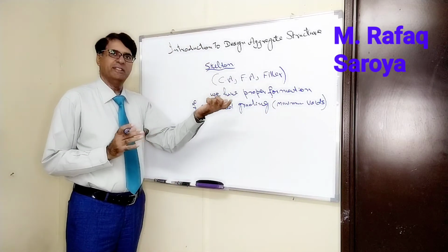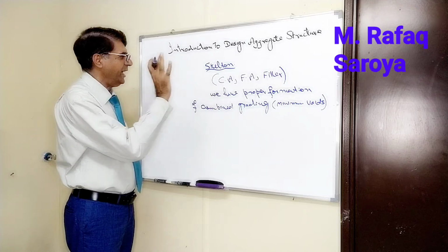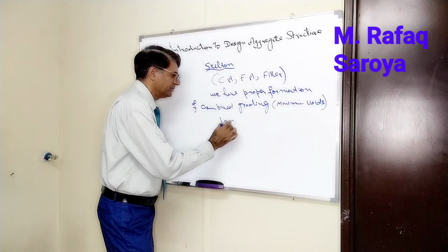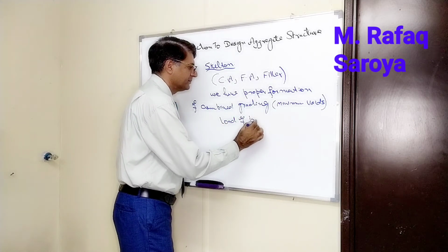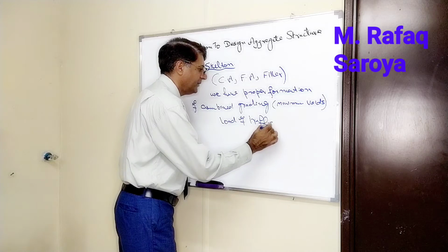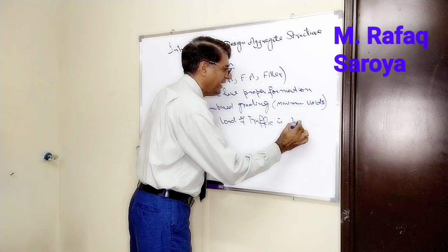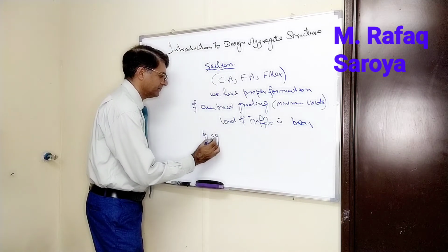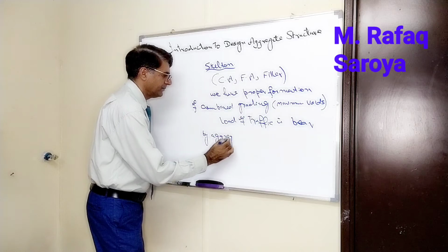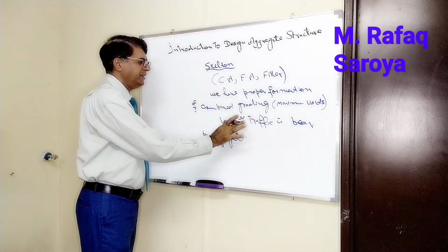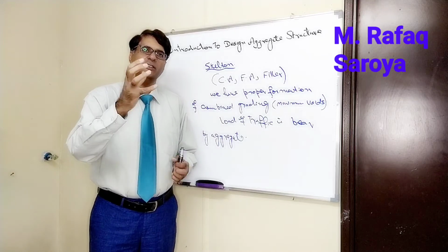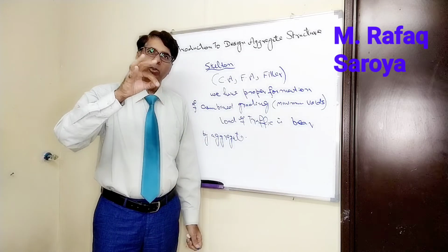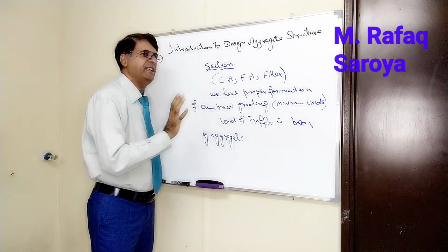When such a skeleton is formed, here I would like to tell you, the load of traffic is borne by the aggregate. You see, keep this in mind. The binder is just going to combine the aggregate, and all the load of the traffic is sustained by the aggregate.